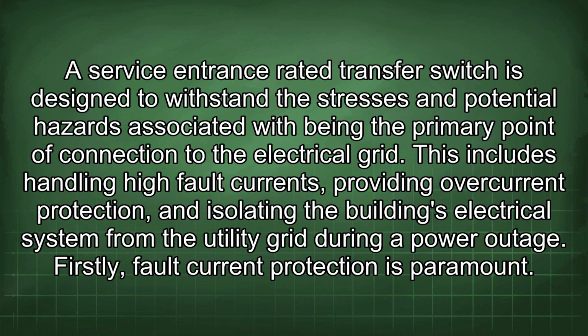A service entrance rated transfer switch is designed to withstand the stresses and potential hazards associated with being the primary point of connection to the electrical grid. This includes handling high fault currents, providing overcurrent protection, and isolating the building's electrical system from the utility grid during a power outage. Firstly, fault current protection is paramount.